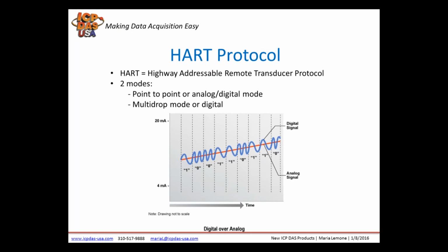Usually current industrial control and monitoring systems communicate over 4 to 20 milliamp analog wiring. Hart protocol can send and receive data over 4 to 20 milliamp analog wires and communicates the data over digital signals as well. The data can be read by all smart field devices.